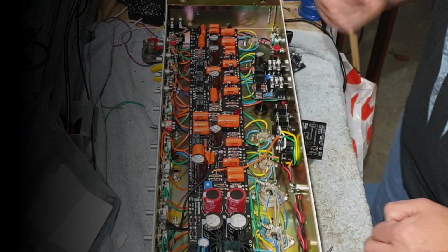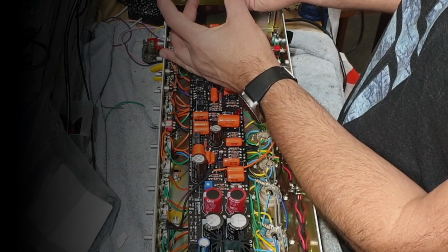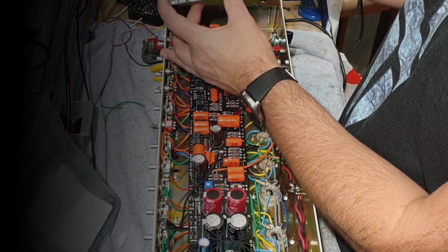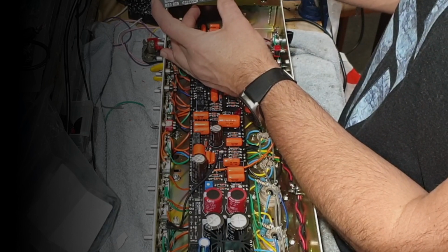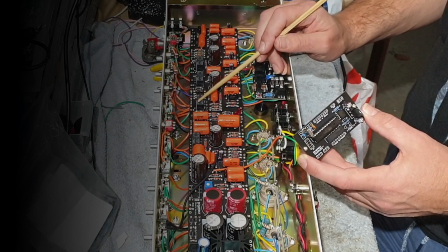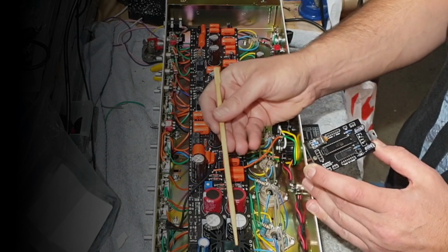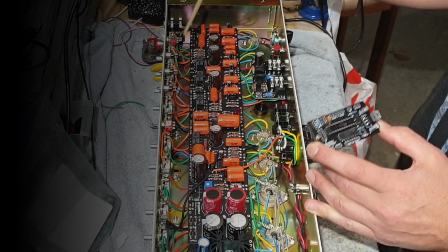Let's do that next. The MIDI board needs a 5-volt DC supply. These logic chips all run on 5 volts, which is very common in electronics. Now, if you've done 5-volt relays on your main board, so you weren't doing 12-volt DC heaters, let's say you had a 7805 regulator and 5-volt relays, which I know many people do.